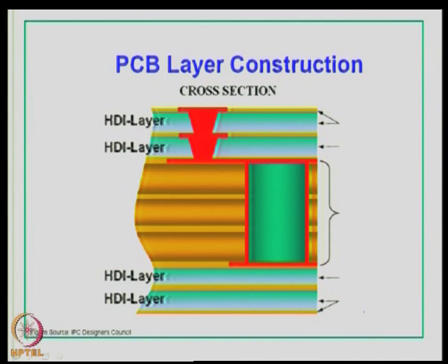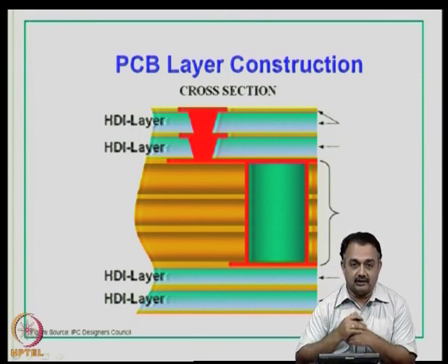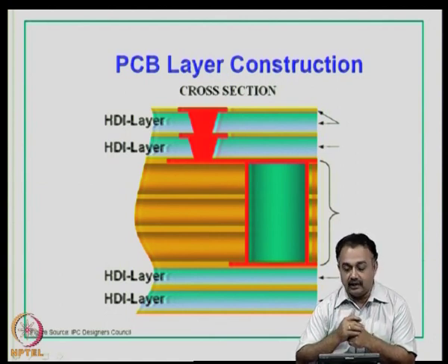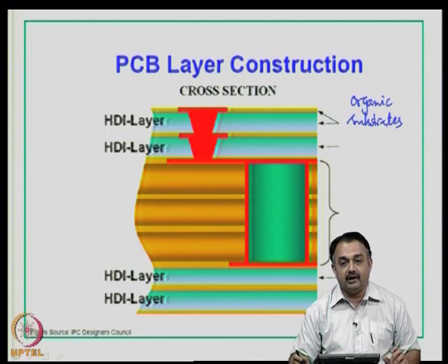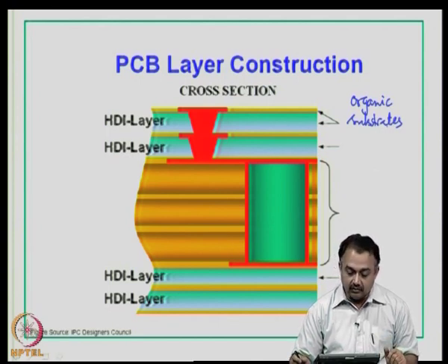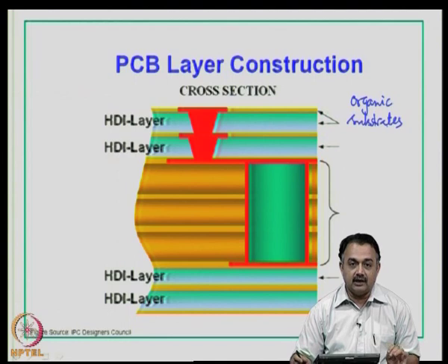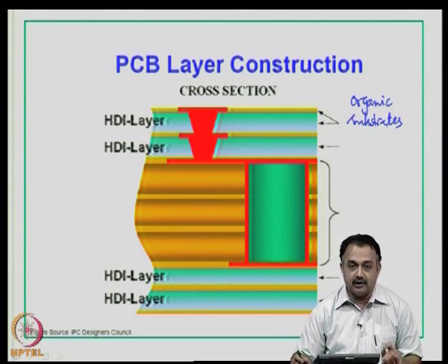Now, we have been talking about printed circuit board or organic substrate which resembles a printed circuit board in these packages, in a BGA package or a CSP, for example. And you must know that these organic substrates that are being used which support the die have very high density interconnect structures. So, I want to pull out some of the slides which normally we discuss in the technology to give you some idea about what a cross section of a organic substrate will look like.